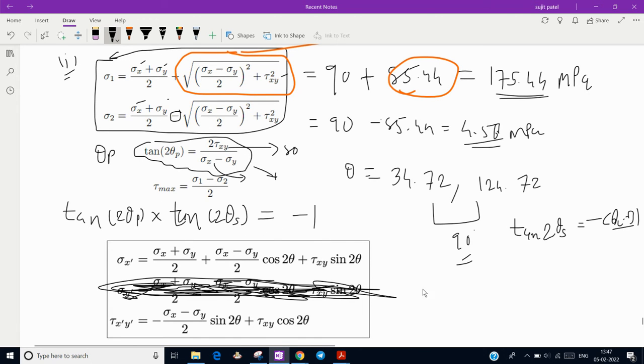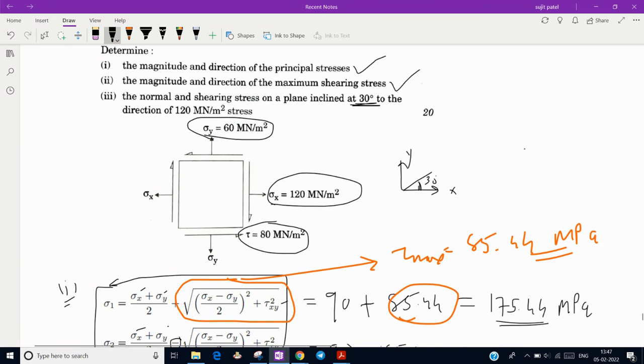So you will get the theta s value as minus 10.27 degrees. Sorry, not Celsius, it's my mistake, because after a long session of thermodynamics you get used to degree Celsius. But here it is minus 10.27 degrees and 79.73 degrees. What this minus means is that if you draw it on the Mohr circle, this minus 10 will be on the negative side, in the fourth quadrant, the value of the maximum shear plane, and the other one is 90 degrees apart.